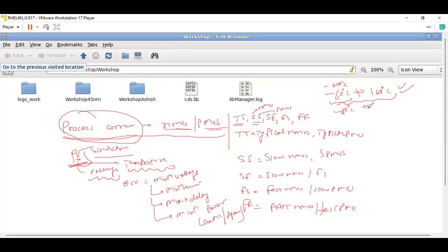And what is the maximum temperature that you see? You see in Rajasthan 52, 53 degrees centigrade. So you test your IC to work up to around 70 degrees centigrade. You test on different temperatures depending on the application of your IC, and this is called temperature variation analysis.